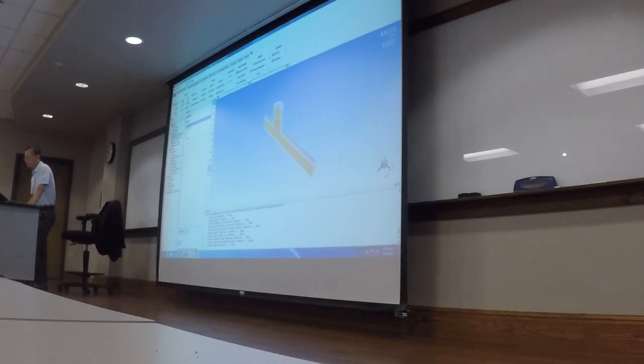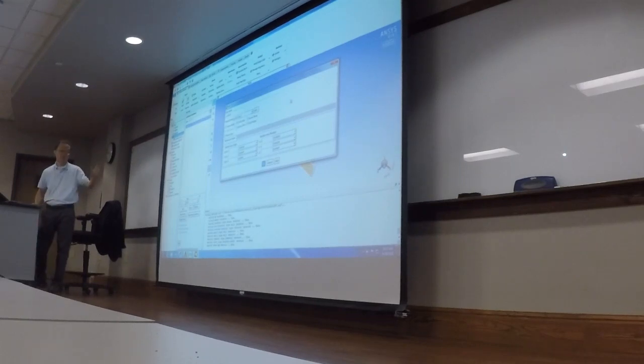Next, cell zone conditions. Junction 1. It's a fluid domain. Yes. Edit. Very important, material name is water liquid. The default is air. No, we have water here. Okay.